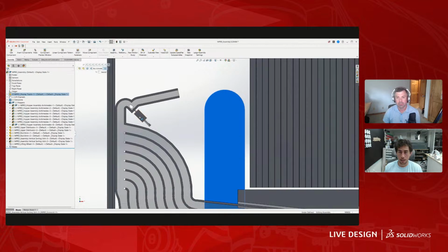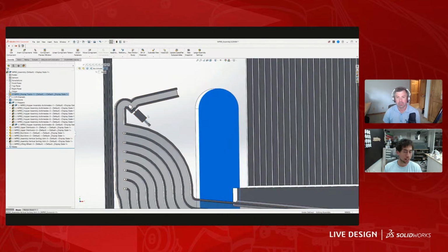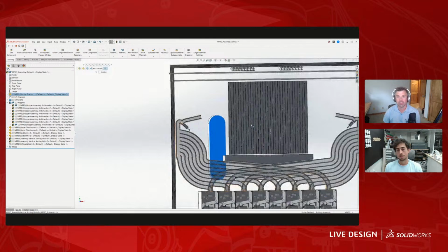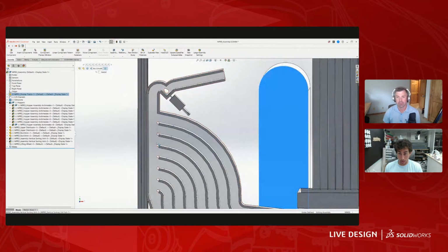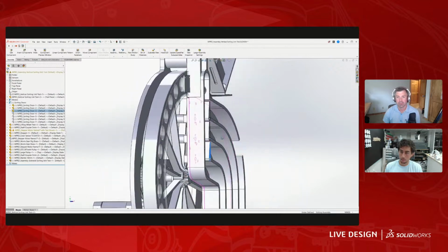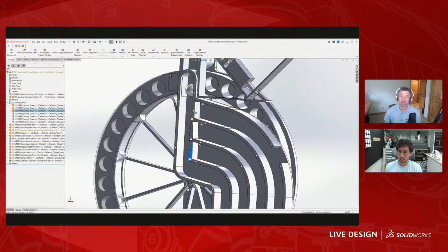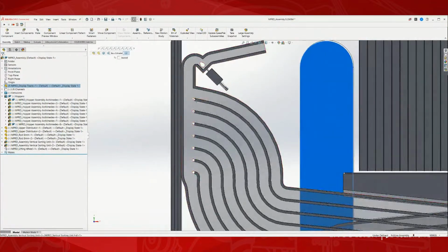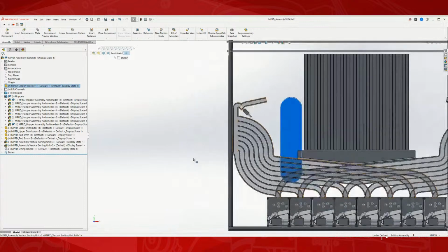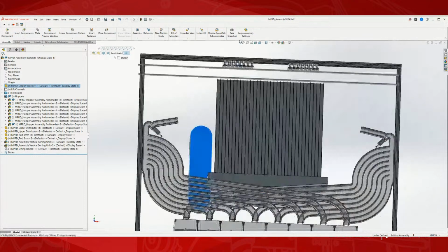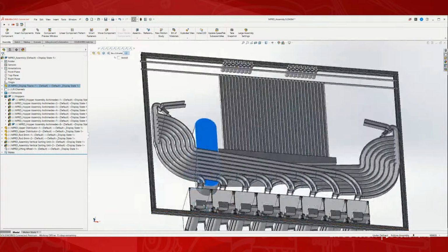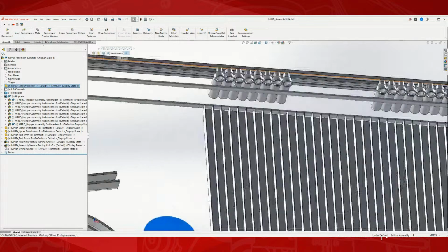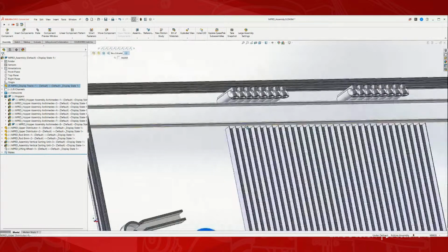There's a solenoid here to eject the marbles. A lot of people have asked me, why not just run the marbles past the color sensor? I've tested that, and it's just not accurate enough. But each one of these holes is going to be powered by one of these small motors, which controls these gates. That's going to be 1, 2, 3, 4, 5, 6, 7 motors there. And each one of these spouts is going to be connected to each one of these gates with a switch I've decided to go with, to know when it's ejected a marble or not.